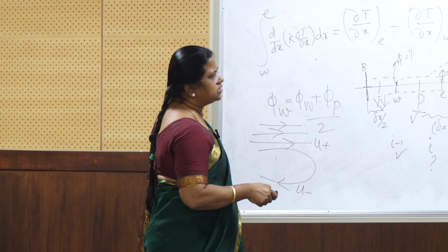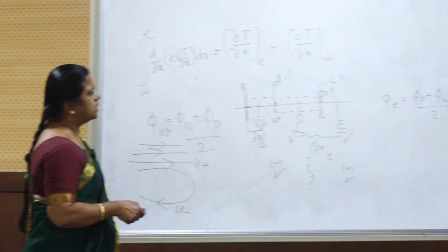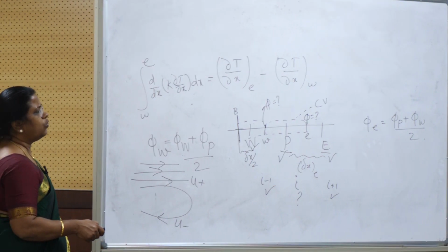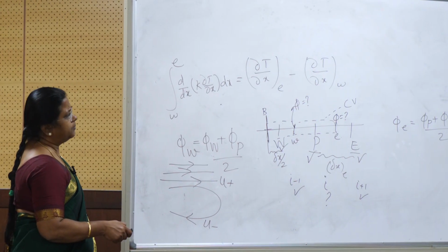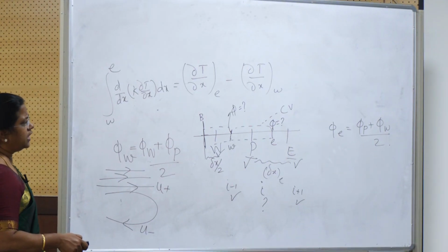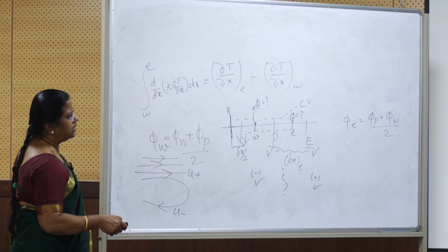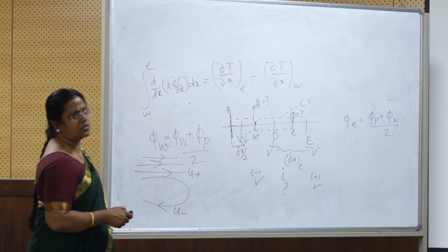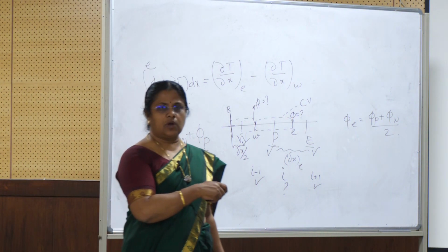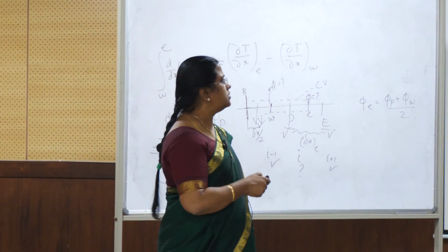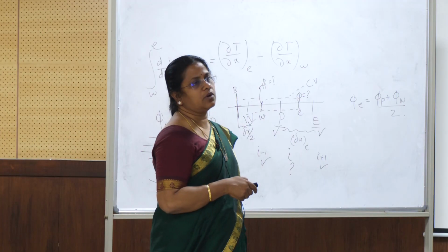K is a constant, na? It is given here. Conductivity K equals 1000 watts per meter per Kelvin. Cross-sectional area is the delta X we have to multiply. That area is given to be 10 into 10 to the power of minus 3 meter squared. Okay, we will solve this one and we will draw the graph also. How that temperature distribution is taking place in this one-dimensional rod.